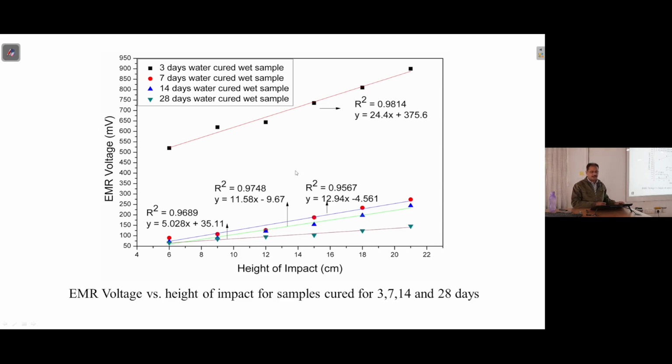That is one thing. Also, we keep soaking it with water, so it continues to absorb that, and that water becomes part of the reaction. And then this CSH gel, as it is called, usually has all the oxides: calcium oxide, and then silicon oxide, and then water also, of course. Together this gel formation takes place, and that is how it gets solidified or becomes a solid strong material.